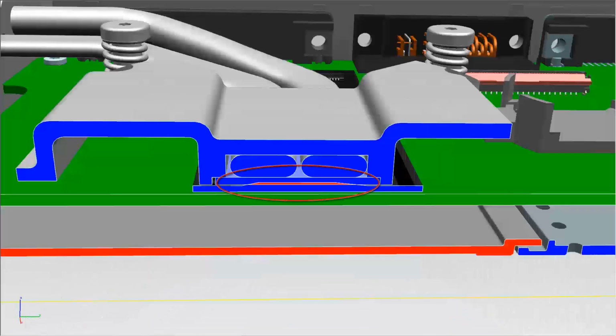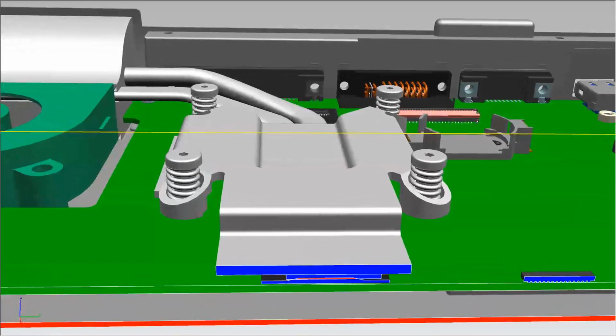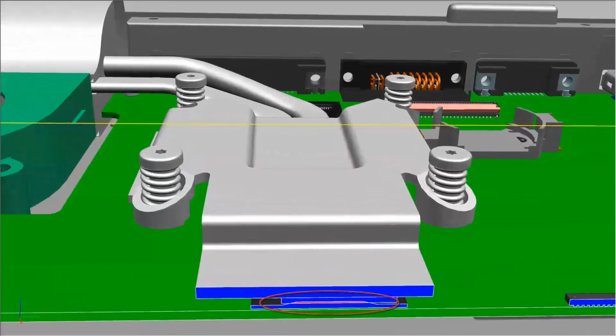In this cross-section, the gap between the cooling plate and the CPU needs to be between 0.42 mm and 0.62 mm to accommodate the thicker 1 mm cooling pad required for the new processor. Excessive pressure from smaller gaps could damage the CPU, while larger gaps could reduce cooling effect. The gap between the cooling plate and GPU has a similar clearance requirement.